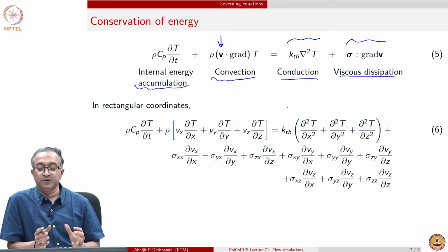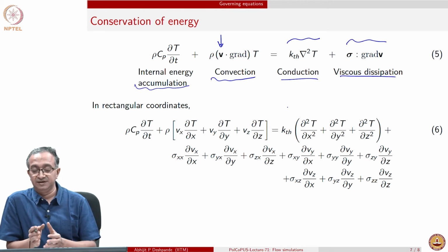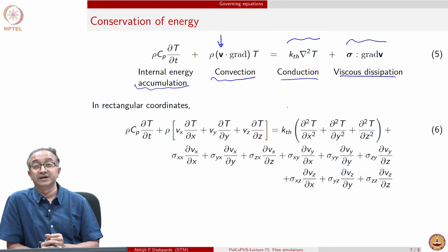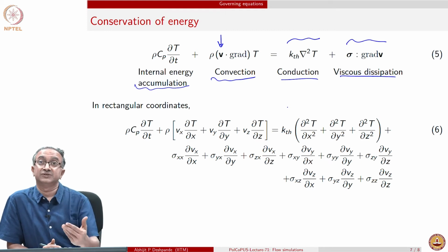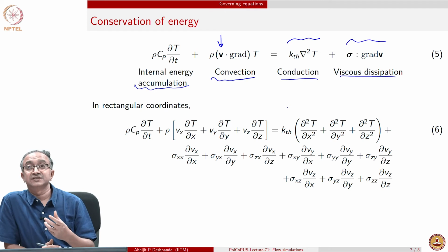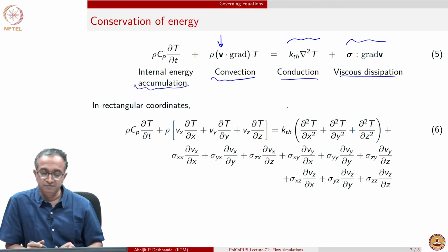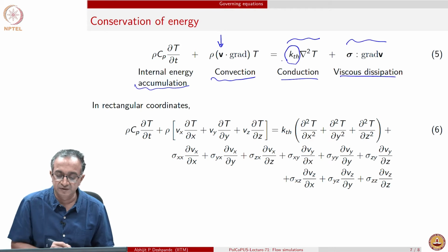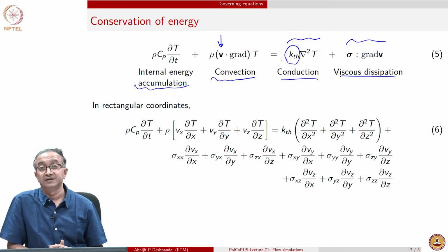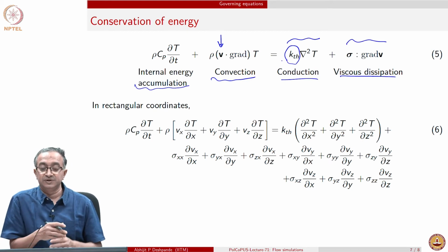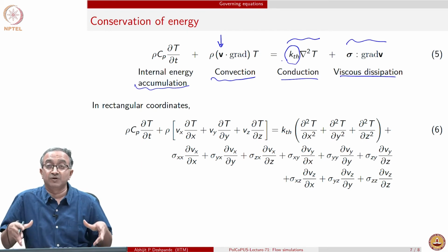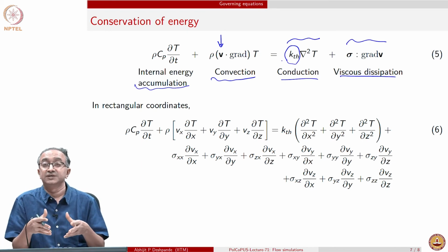And in case of polymers, given that viscosity is very high, generally viscous dissipation will be very high. Additionally, in operations such as injection molding or several operations, the shear rates are also very high, gradient of velocity is there quite high. So, again viscous dissipation is dominant. Over and above, generally the conductivity of polymer is not very high. In fact, we use polymers as both electrical and thermal insulators many times. So, the ability of the overall mass of polymer which is being processed to conduct the heat away is limited.